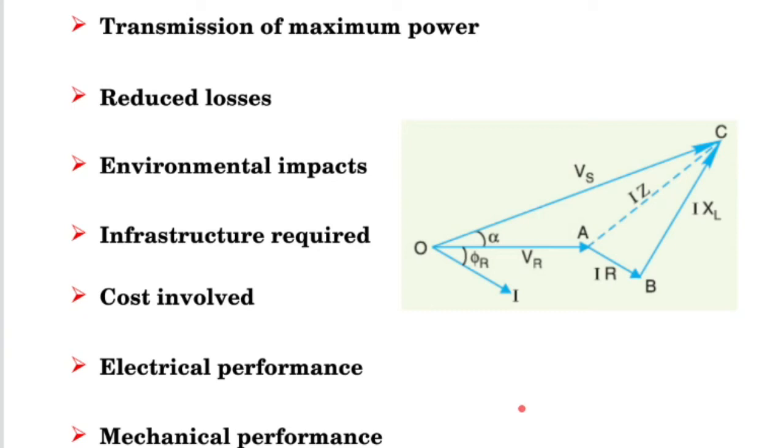So we run those transmission lines out by the outskirts of the cities, and from there we go for lower voltage lines like 132 kV. We can also go for 66 kV, and we can also go for 33 kV, 22 kV, 11 kV, and then finally coming to that 400 volt three-phase, from where we can take single-phase supply and three-phase supply as well.